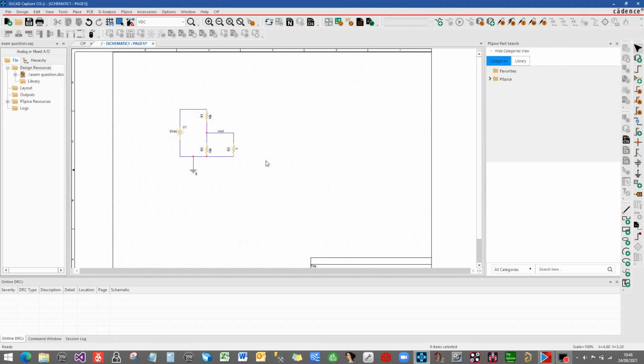So what would be the voltage on V out if this resistor has a value at which maximum power transfer takes place? The first thing we need to know is, for maximum power transfer, this resistor value is somewhere between a short and an open. For maximum current transfer through that resistor, it has to be a short. For maximum voltage transfer, it has to be an open. And obviously maximum power transfer is going to be somewhere in between.